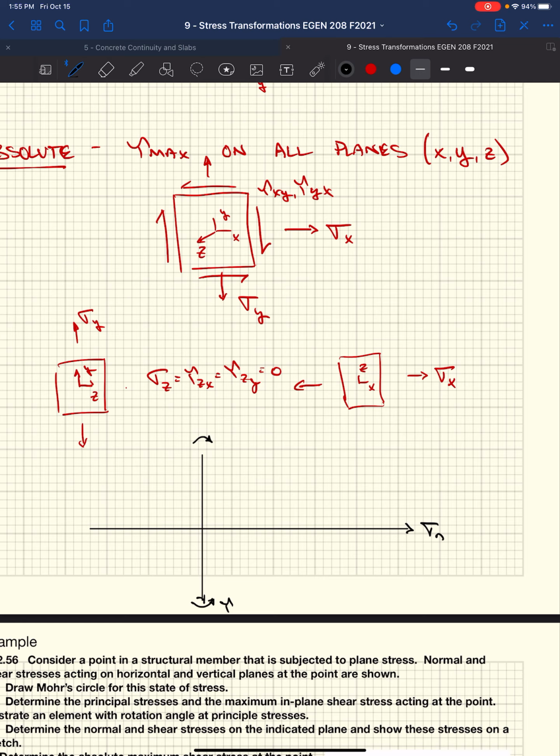And say we had an initial stress state, just like we did for the flagpole. We've got X and Y coordinates on this block. We get stresses. We've got, say, a tau XY, which is a tau YX, and we have normal stresses just like we did. And we plotted those points. Maybe it was here, maybe it was down here. We're going to get a circle. Maybe it does something like that.